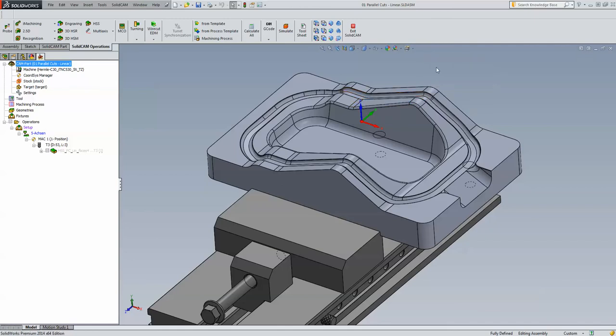And what normally happens when using the linear option is that we all know that linear works very well in shallow areas, on shallow surfaces, okay? But when you have a steep surface, linear doesn't work as nicely. However, we can control it now to get a very good surface finish even with linear, if you use a ball end mill.